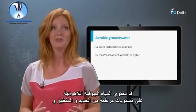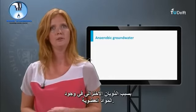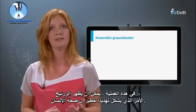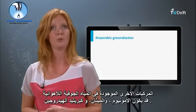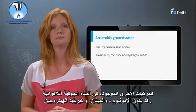Anaerobic groundwater may contain elevated levels of iron and manganese because of reductive dissolution in the presence of organic material. In this process, also arsenic may be released, which is a serious threat to human health. Other compounds found in anaerobic groundwater may be ammonium, methane, and hydrogen sulfide.